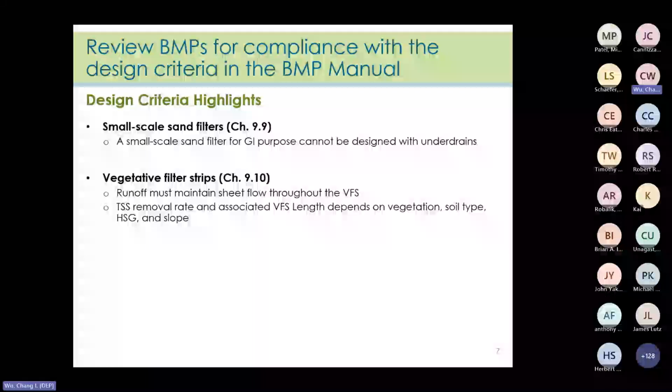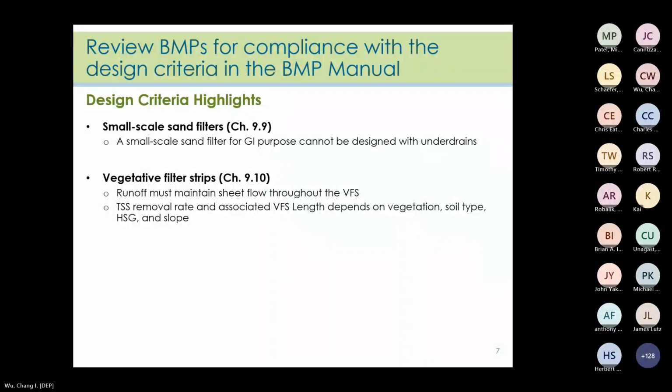For the vegetative filter strip, you have to maintain the runoff as sheet flow throughout the vegetative filter strip area.